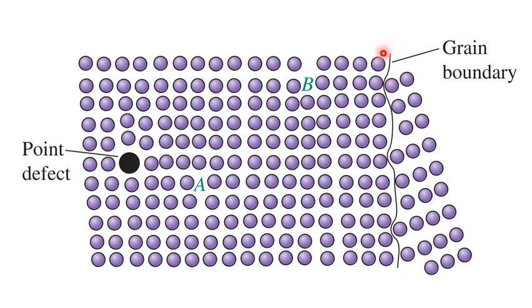The grain boundary, as we explained earlier, is the area where the atoms are not properly bonded. The dislocation will stop and block here at the grain boundary. The dislocation cannot move through the grain boundary. Thus grain boundaries do the same job of strengthening the material,